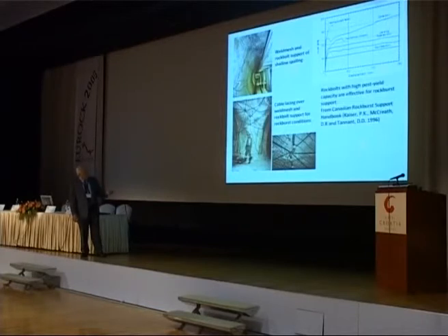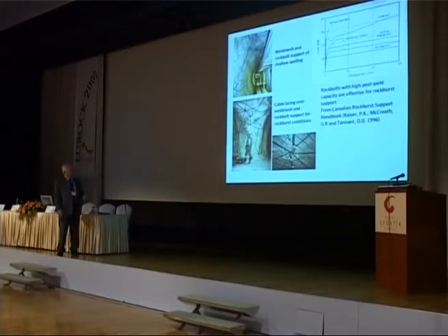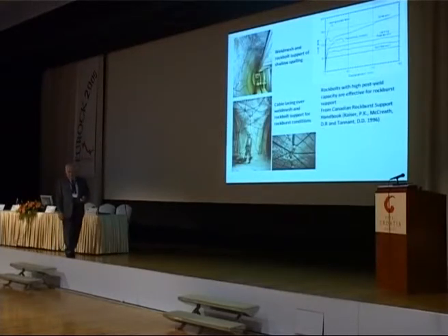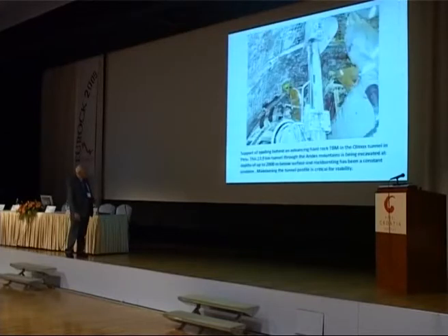Also on the rock bolting side, rock bolts with a high yield capacity so that you can get a large deformation while they maintain the load. And that applies to bolts like Swellex or cone bolts, which are a special South African design of bolts that slide in a ductile way. These are all necessary tools in order to control the process of brittle spalling.